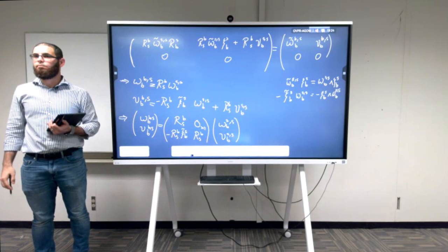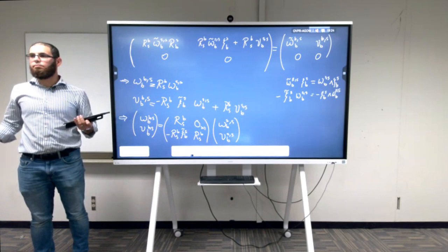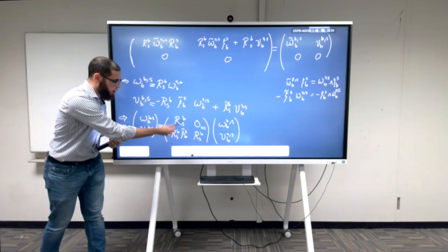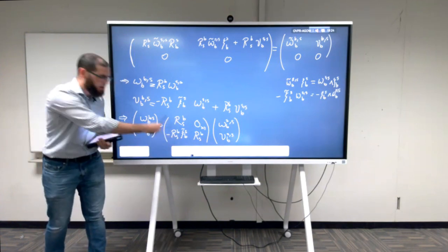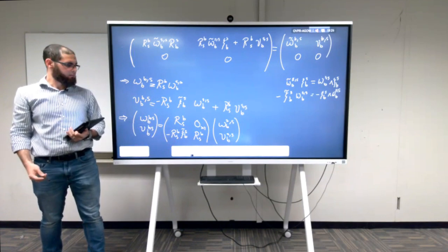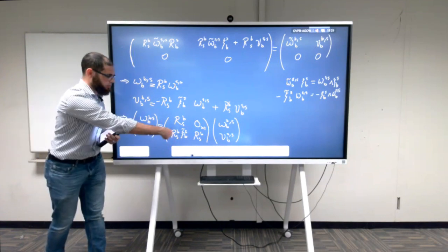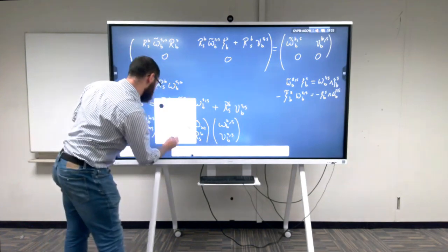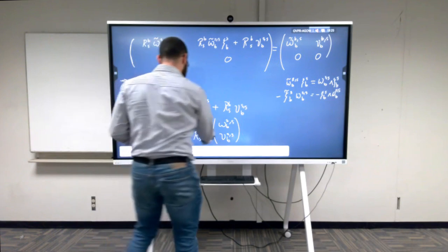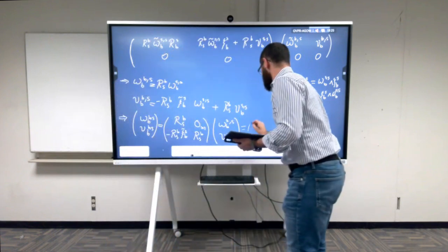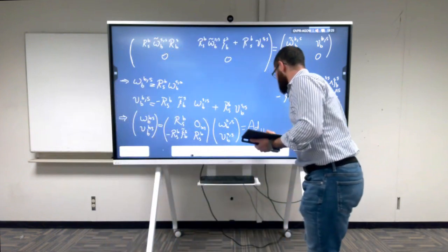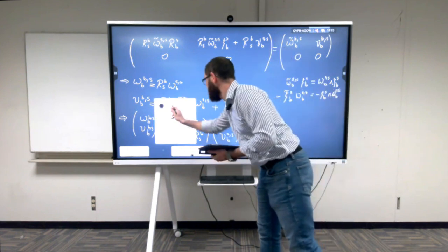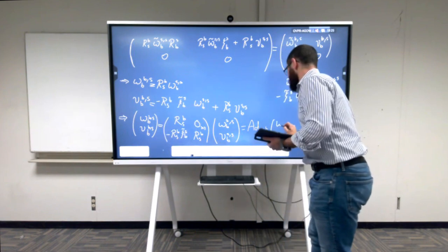Clear? Looks nice. So this is a 6 by 6 matrix. It's a function of R_SB and psi_BS tilde, and R_SB again. So this is what we wanted to call it. Everything in here, this part, I can rewrite as Ad_H_SB multiplied by the vector omega.